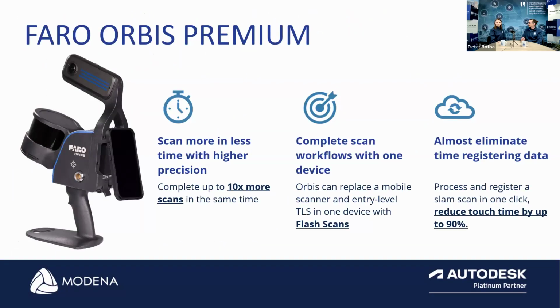Right. Some benefits that we have on the scanner is we can scan a site very quickly. We can also scan a site within one scan loop, which is quite nice. You can scan a very large space in a couple of minutes, where the other way of scanning would take much longer. We have a comparison for that at the end as well. And there's no registration required for the one loop scan. The only reason you would do the registration is if you do more than one loop on the area that you're scanning.